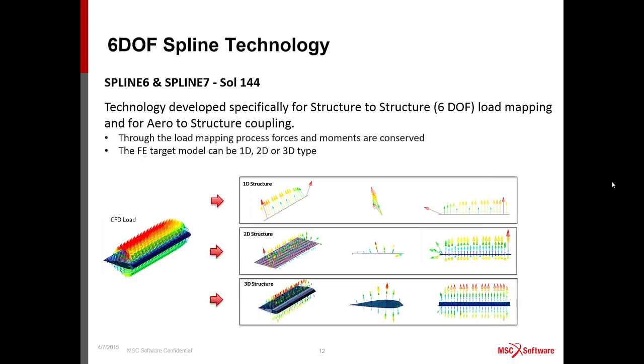Okay. The important thing that we have to know is that when we use this procedure, and we transfer the load from the CFD to the structure, the force and moments are conserved. First of all. The second important aspect is that we can use a general structural model. We don't have to use a structural model with the same shape as the CFD one.